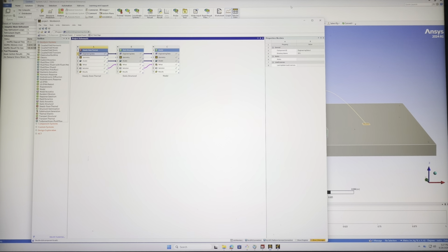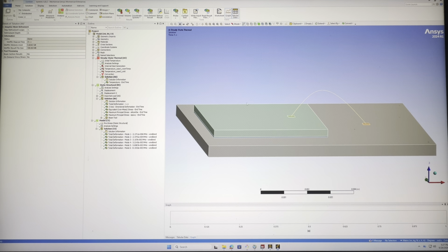So before I start, I would like to show you the geometry of what I have. This part, the part that I'm highlighting, is basically a die, a silicon die, which is typical in semiconductor packages. And then there is an epoxy layer underneath it. And at the very end, you have a substrate. The substrate, the gray, is basically your printed circuit board. It is layers of copper and FR4 that make up your printed circuit board. And you have these gold pads on your, say, silicon and also substrate where the wire bond is connected, and you're able to read out your module.